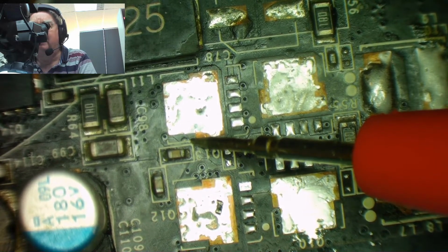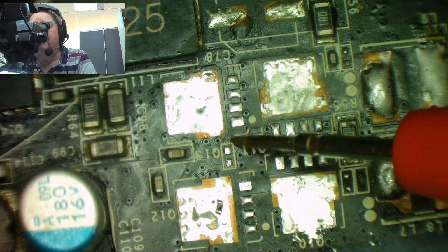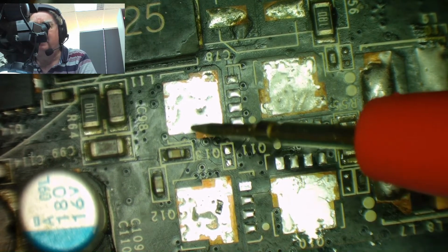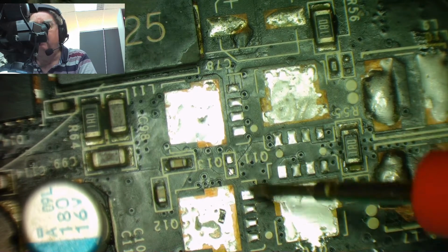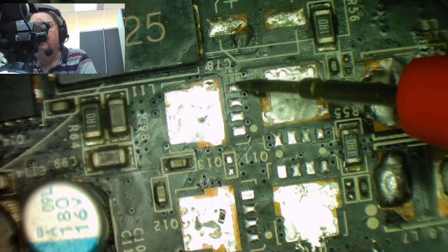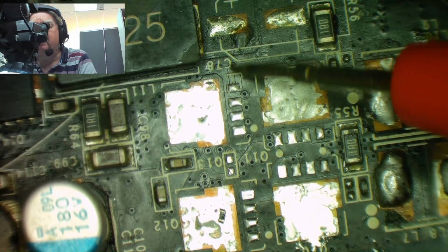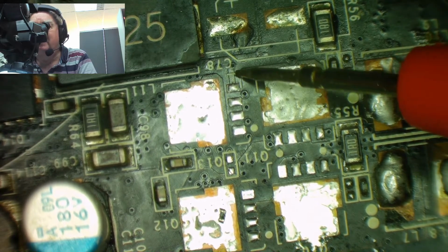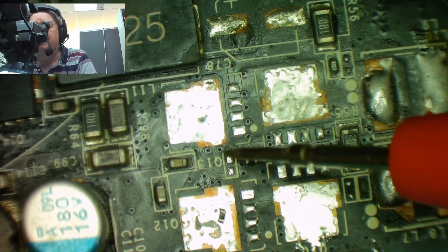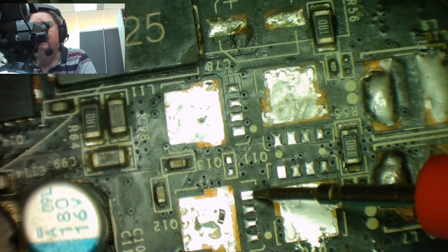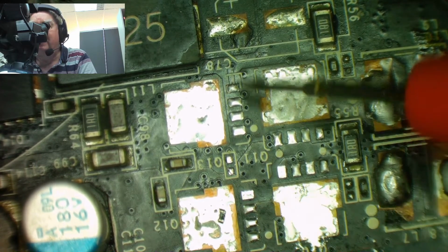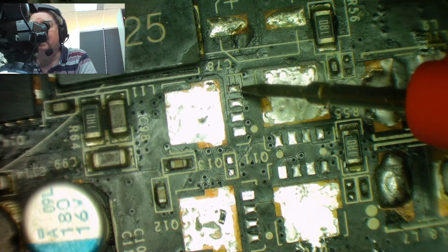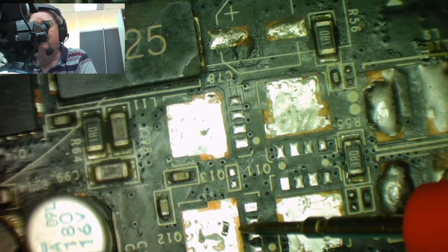to the controller, I would think. And this resistor seems just to be in series from the controller to the gate. This is the other one, and this one just disappears straight down the board. This is the gate of the other one, so I don't see a same resistor here, and I'm guessing that is because it's on the other side of the board. I'm guessing there's another resistor of the same value as this on the other side of the board. And if we can see what that is, then we can replace this one.